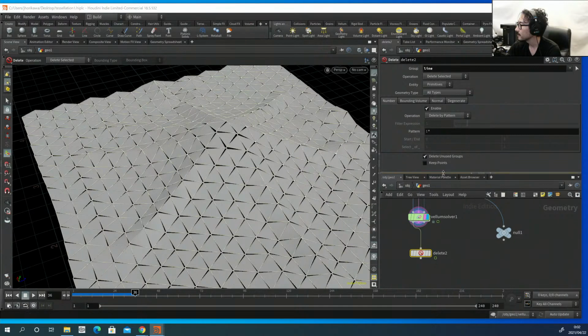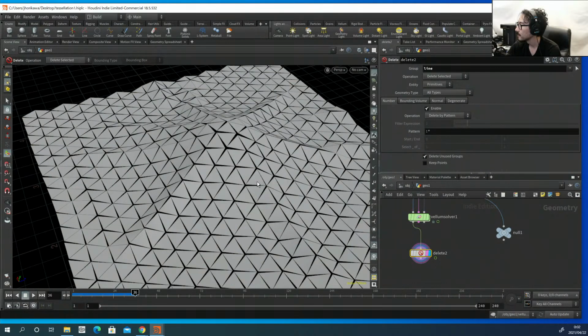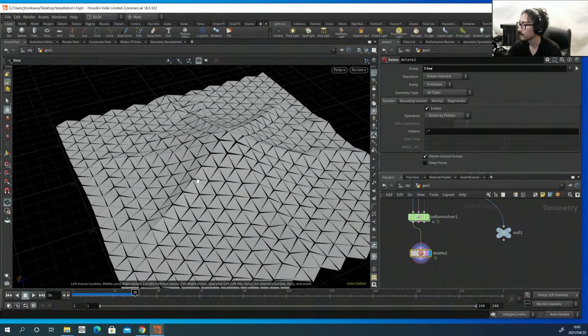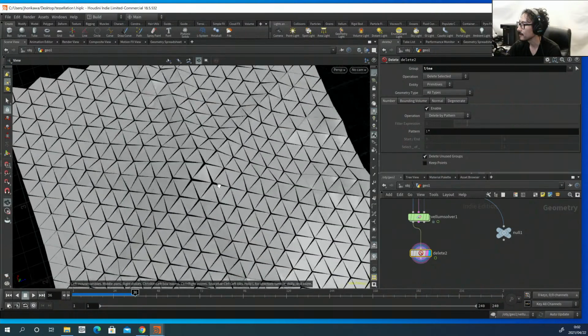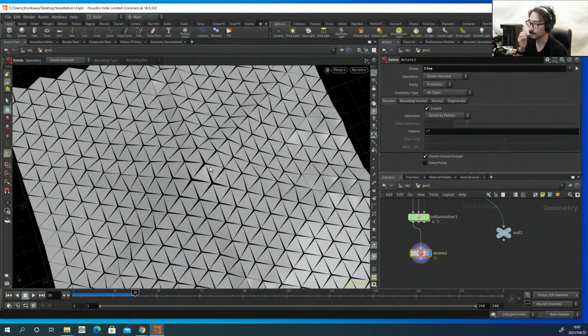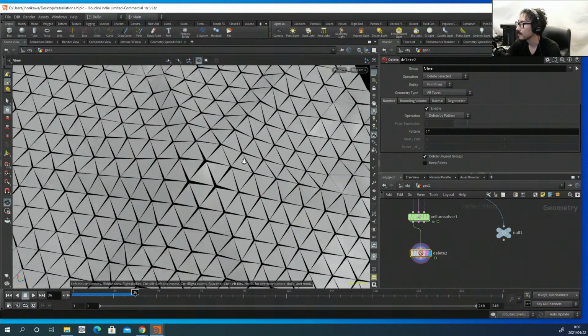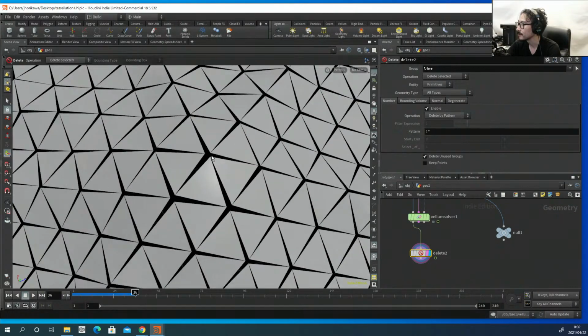Okay, and at the last, let's also delete these edges as a visual. Delete the line. So it looks like this right now. So this is a bit too stiff. I want to have more openings to have more variations between the gradient openings result. Okay, so to do that, I need to control the stiffness of these center constraint curves.